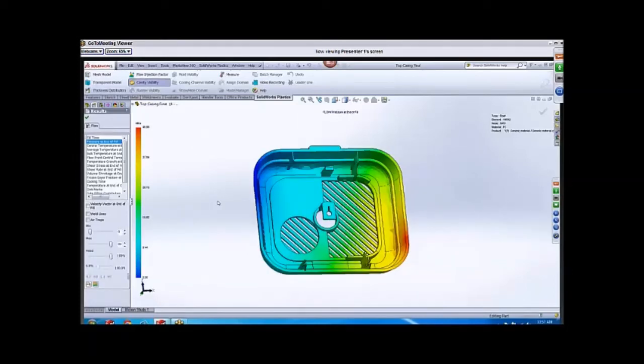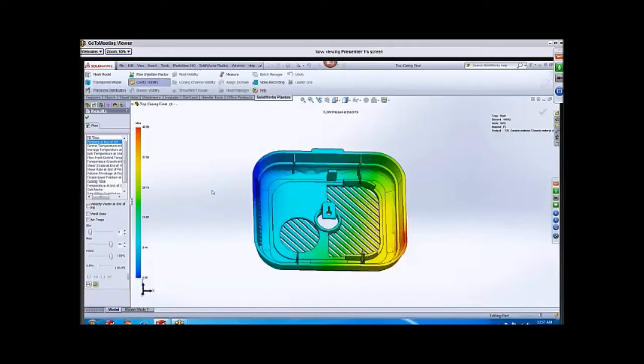And if you can imagine it, if you need a lot of pressure to fill up a plastic part, you'll need a much larger machine than for a part that is easy to fill up with plastic. So if you can get a smaller machine, you'll potentially save a lot of money that way. And right now, we're working with a fill of 47 megapascals, which is a lot of pressure that the machine is going to need to fill.